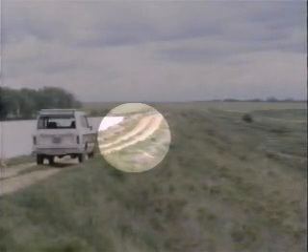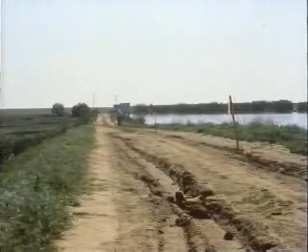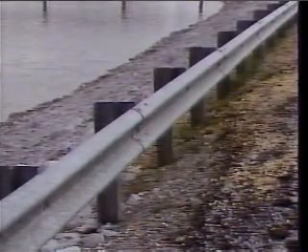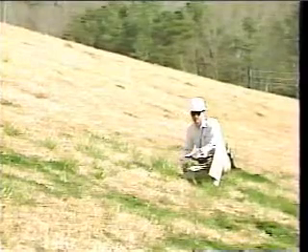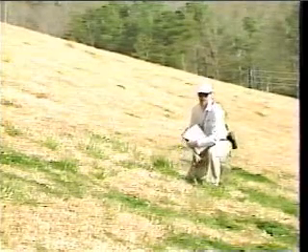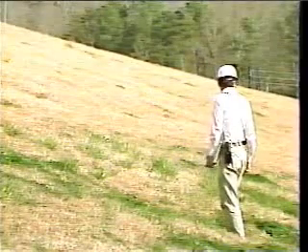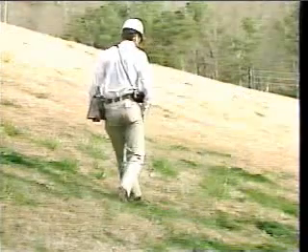Depressions and sinkholes are two closely related features. Depressions are usually the result of localized settlement, but can also be widespread. On the crest, this could mean loss of freeboard with possible overtopping of the dam during flood. One way to detect depressions in the crest and slopes is by sighting along fixed points or along the slope. Most of the time, depressions don't represent an immediate danger to the dam, but their location, size, and depth should be written down. Make it a point to check on these depressions often until you're sure movement has ceased.